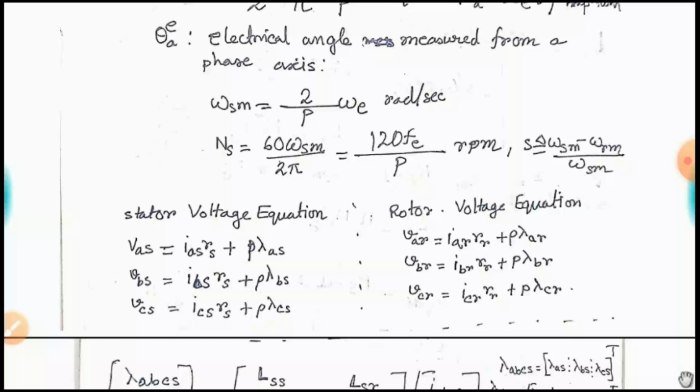It has 3 slip rings to take the rotor winding terminals out for external availability, and at those slip rings electrical sparking takes place. This makes the whole system a bit fragile, and not as compact as the squirrel cage induction motor.